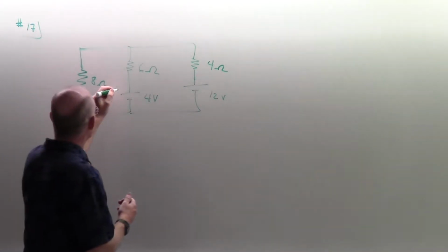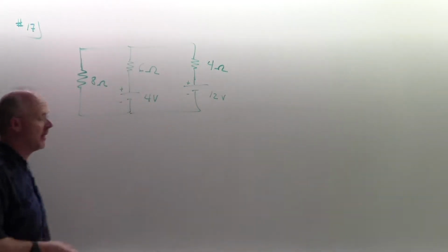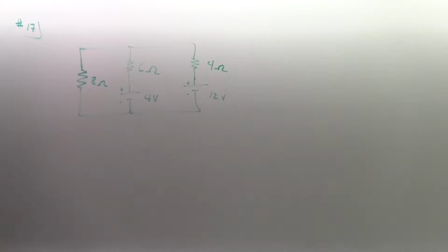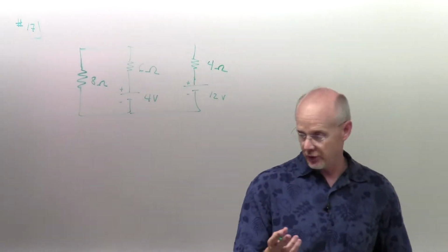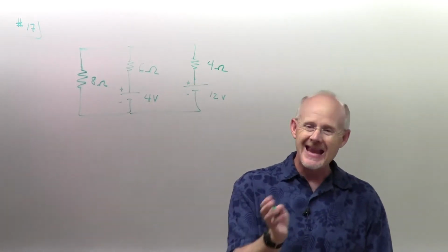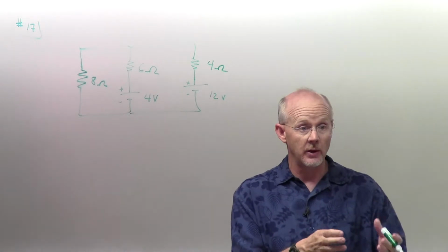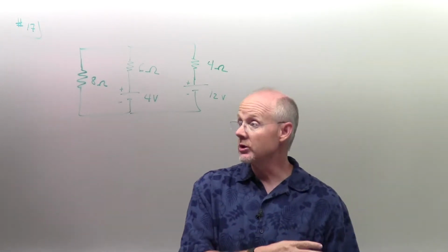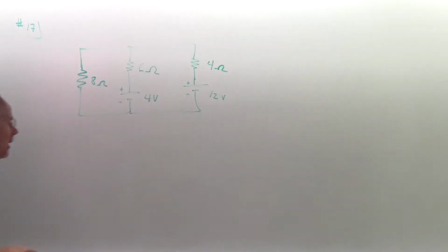And again, maybe putting the plus and minus to kind of remind myself that the longer leg is for the positive. Pick a direction of the current. And again, just wanted to remind you, you're really picking a direction. You're not saying for sure which direction the current is, but if we work out the math and we get a negative number for one of our currents, that tells us really we are going the wrong direction, okay? And so that's really what we mean.